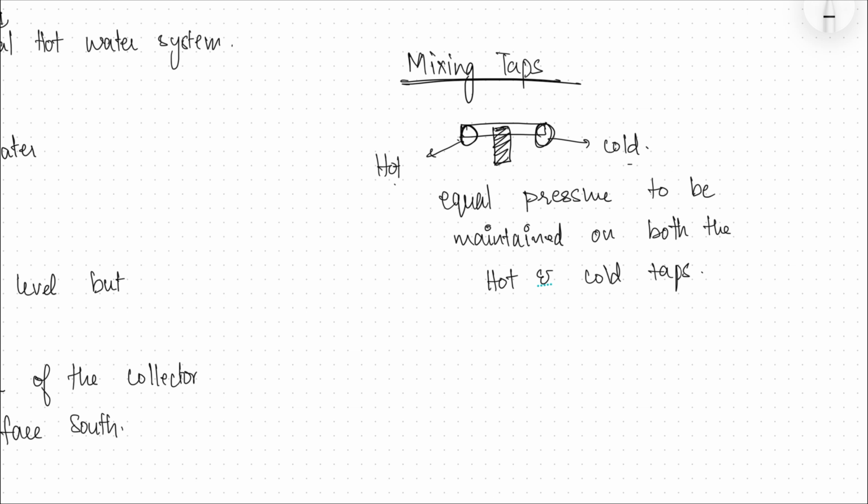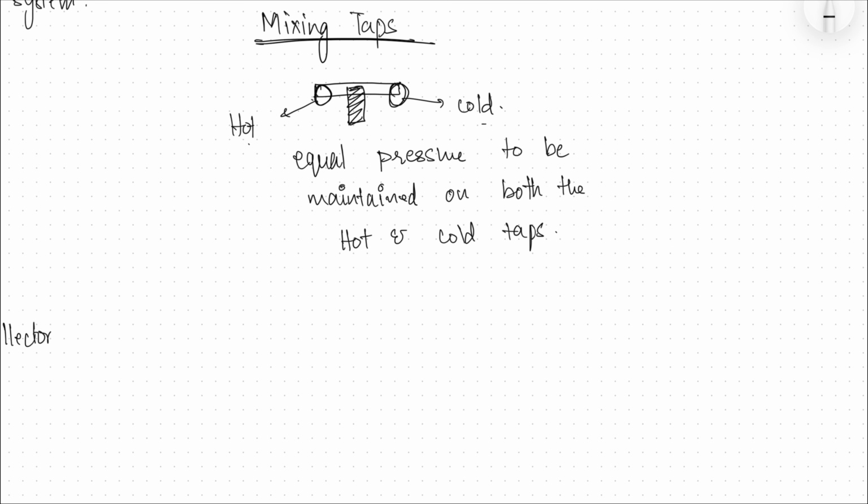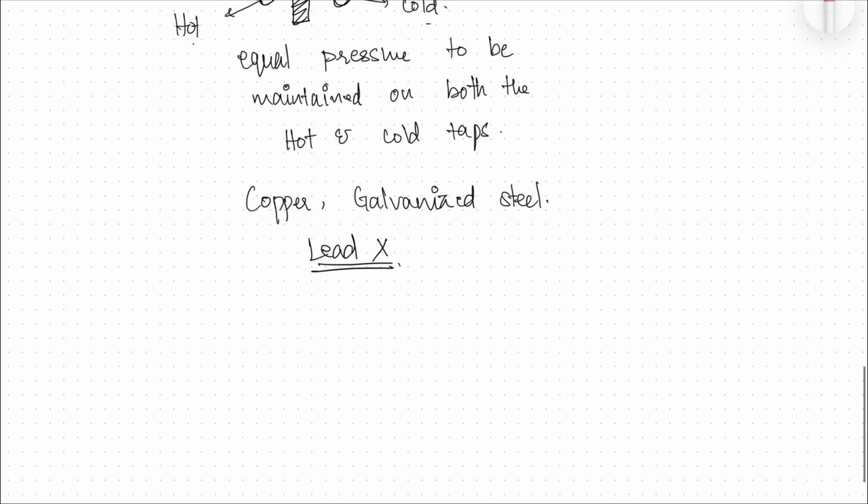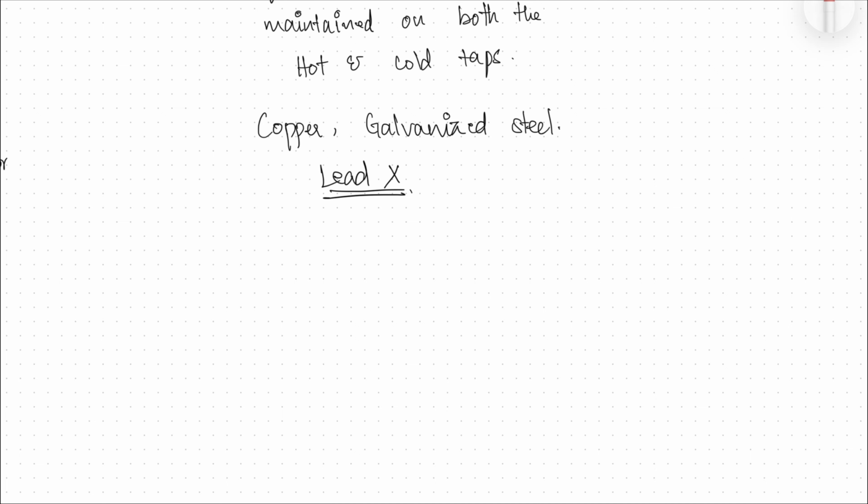Then, if you see materials, copper is widely used. You can also use galvanized steel, and lead should be avoided because it can dissolve rapidly due to the hot temperature. It's hot water, right? So the temperature desirably should be a maximum of 60 degrees Celsius.